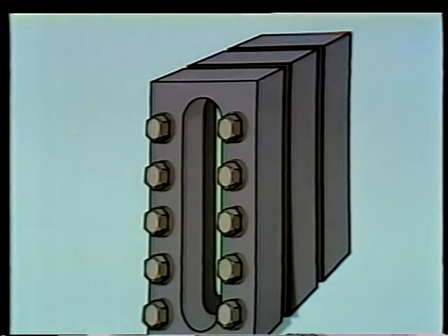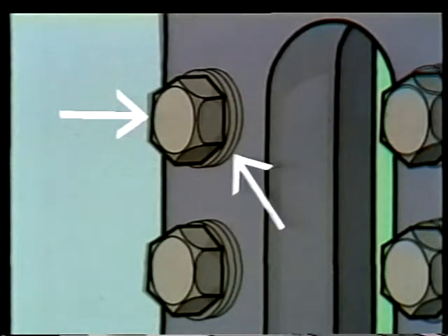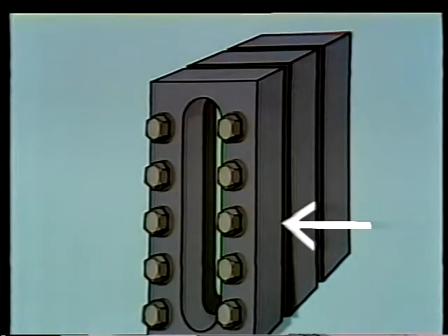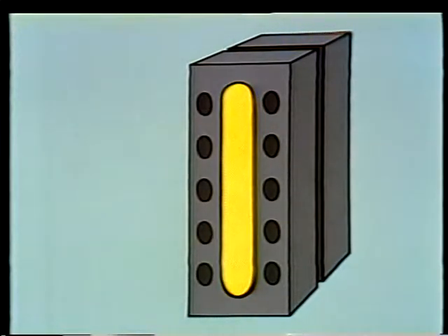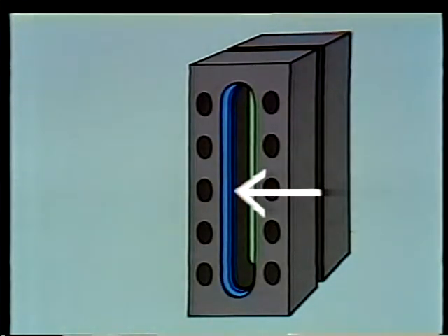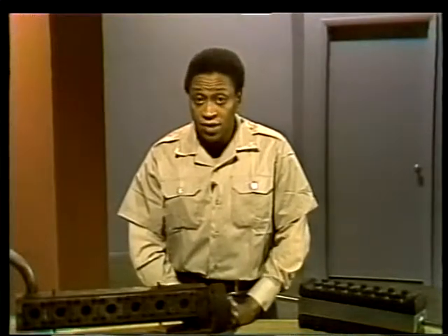Now, a flat glass gauge has several parts that you'll see during an overhaul. These include the bolts and spring washers, cover plate, cushion, glass, mica, gasket, and the gauge body. It's best to disassemble the gauge while it's hot because otherwise the gauge gaskets tend to stick.